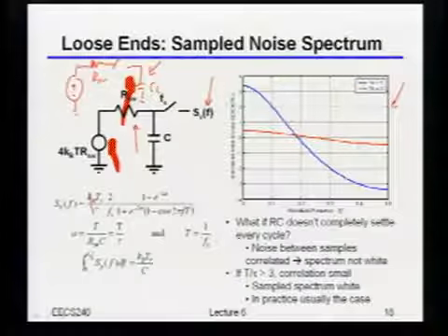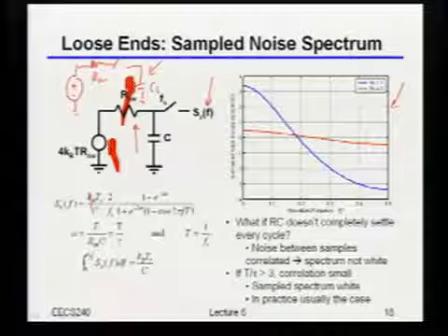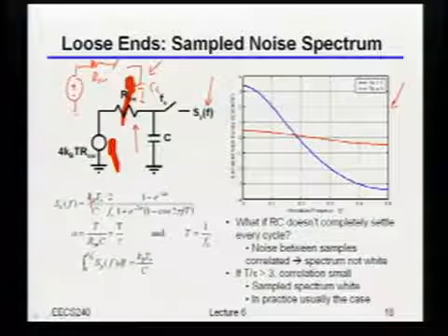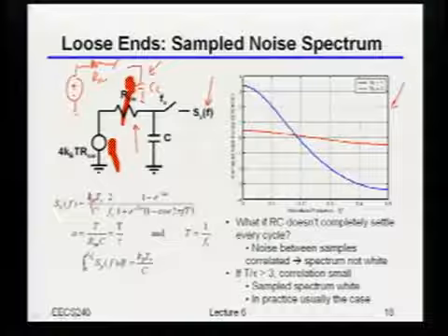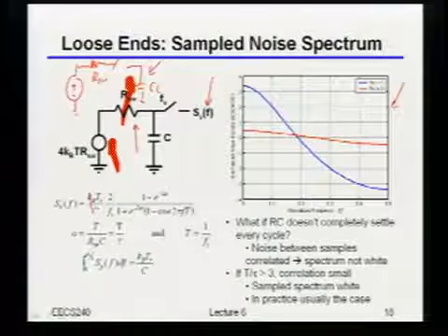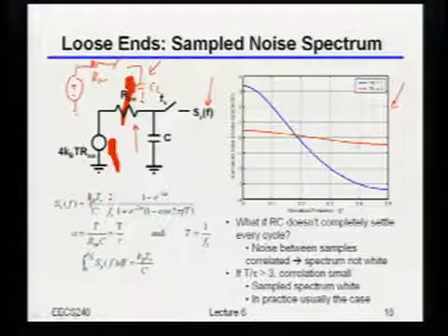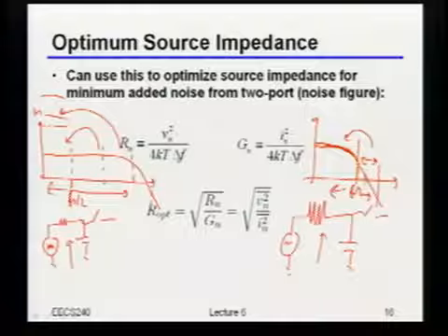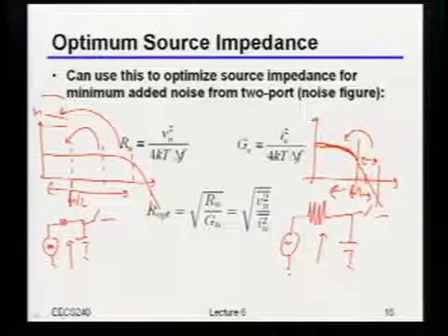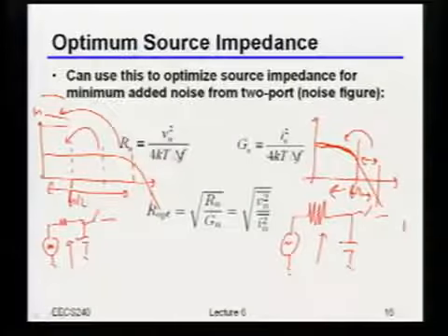It's only dependent on C. Okay, I agree it's only dependent on C, but I've done all this weird sampling and aliasing and all this other stuff. So, you're right, it doesn't change, but why doesn't that change anything? If you integrate it over the spectrum, you're going to add the same amount because... Yeah, exactly, right? So when I do that sampling process, I'm grabbing these chunks and folding them back, but the total amount that added is no different than it was when I integrated over the entire spectrum, right?